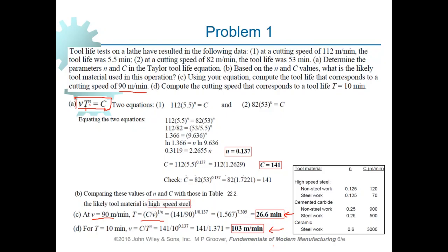If we have limited cutting tools available, we can estimate or compute the cutting speed, which makes it possible for us to proceed with the machining operation. Okay, are there any questions on this? No questions? So, making use of Taylor's equation.